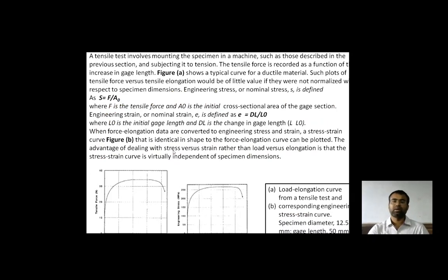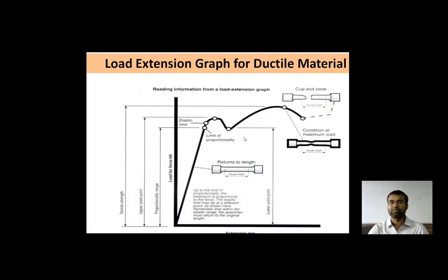And above all, the stress-strain curve plays a very vital role in understanding the behavior of the material during elongation in the tensile test, showing the various stress and strain on the material, and when it breaks down. This schematic diagram shows the exact points: the initial point from zero to the elastic limit, then the limit of proportionality, the plastic region, the upper yield, that is the yielding process, the lower yield, and the ultimate tensile and fracture strength, and so on.